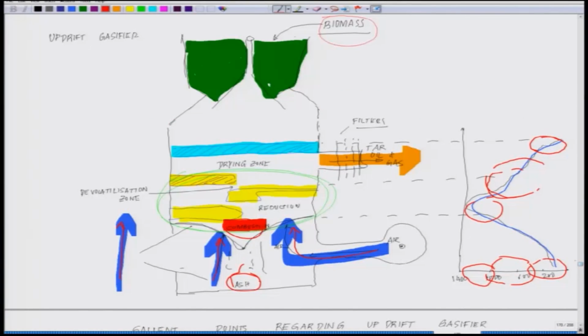So, look at it. Here the ash is getting collected as the air is moving. Here all the combustion and all the chemistry is happening, and the ash which is coming out is now falling down like this through the grate, and it is getting accumulated out here, whereas most of the gas or products which you need, the product gas, is all forming out here in this location.